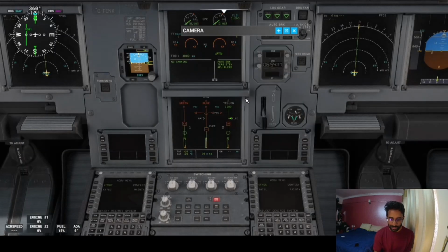Okay. So when that happened, what is happening to your ST page? Did you see? When that cargo door was opening, it's a big door, right? So you need hydraulic pressure to operate that door. So when the ground staff opened the door, the electric pump automatically turned on, which is pressurizing only the yellow system. If you remember from the architecture, it is the yellow system that operates the cargo door. In this case, the PTU does not work. It is inhibited.